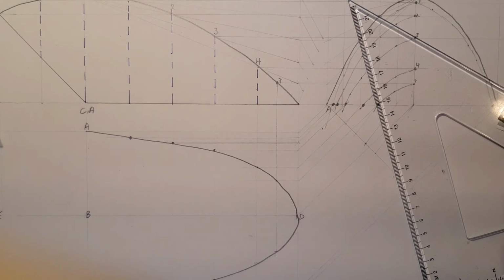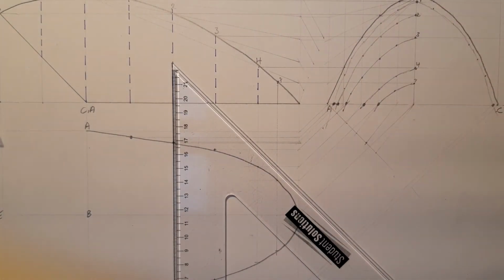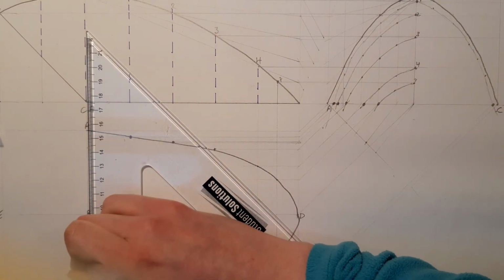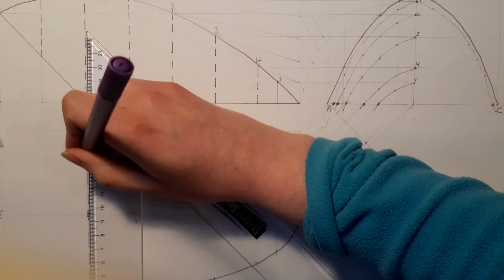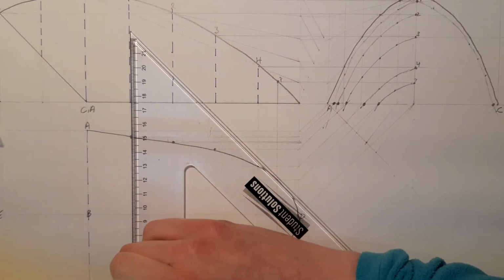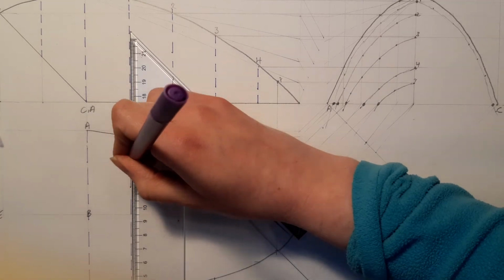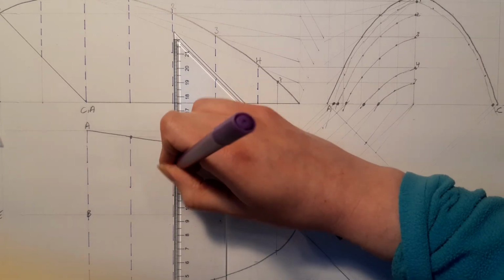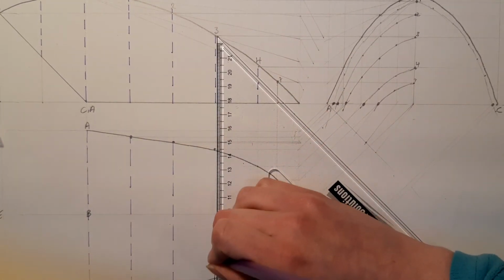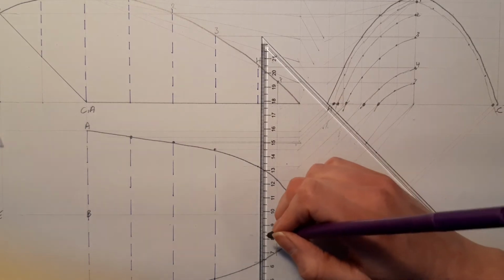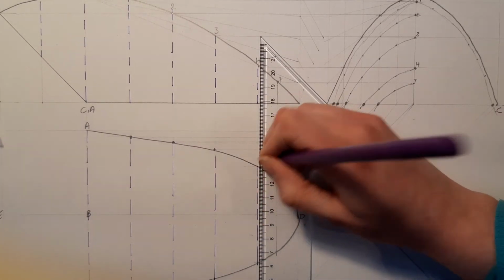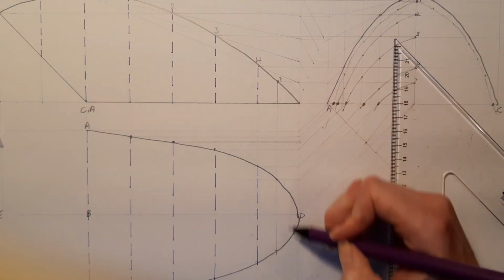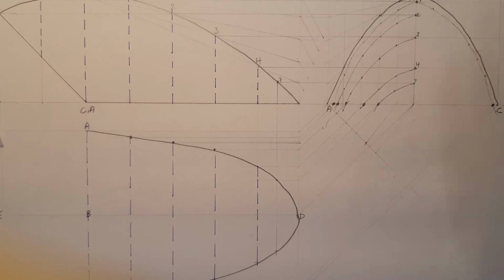Okay, so that's basically it. Now you can put those construction lines in to show the different parabolas that you had. So we had this one first. That was the main generating parabola, it was ABC. And this was line 1. And basically I'm just replicating what the question had. Line 2. Line 3. Line 4. Now I put in an extra line, as you can see, just in order to get that curve a little bit more accurate. You could even put in another one if you wanted to get another point, but you weren't asked to.